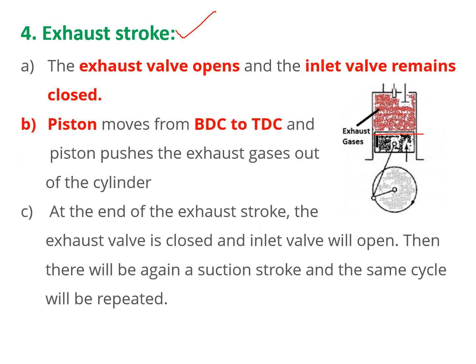Now these are the burnt gases, and at that exhaust stroke, the piston will move from BDC to TDC, and the exhaust valve opens actually when that particular motion starts, and due to that our pressure will drop. Whatever burnt gases are inside the cylinder will escape out from the exhaust valve. During that exhaust stroke, where the piston is moving from BDC to TDC, the inlet valve is still closed, but the exhaust valve opens. So all the burnt gases will escape out.